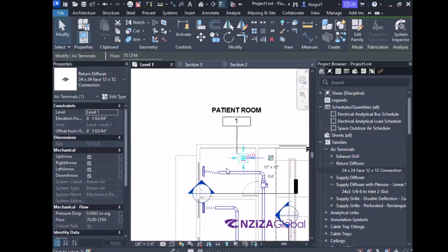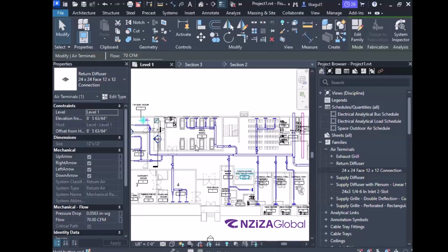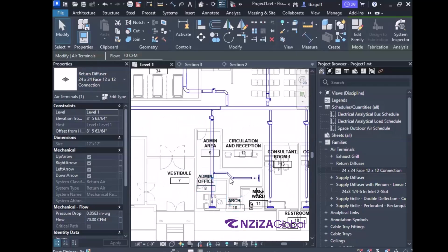Okay. In this case, our logic for positive pressurization was for infiltration. Let's say if this room is somewhere in here, like yesterday, I think Lawrence or Tony mentioned online, like this room over here is an interior room. It does not have any infiltration assigned to it. And if this room was a patient room, it can be at neutral. 80 CFM inlet, 80 CFM outlet. Make sense?